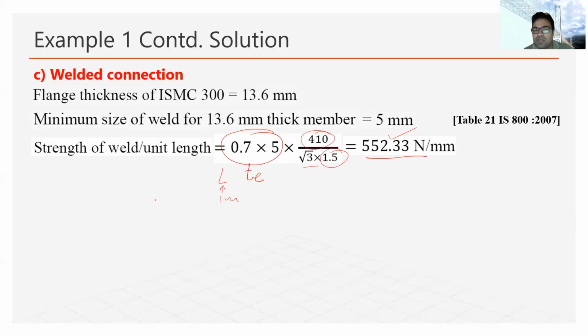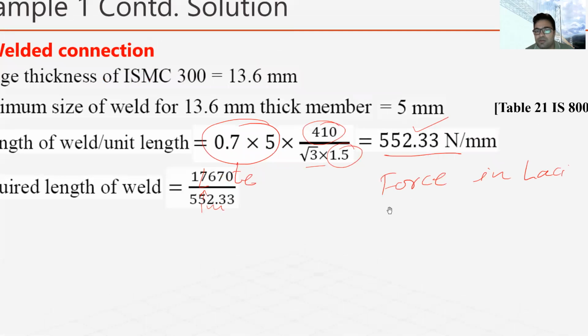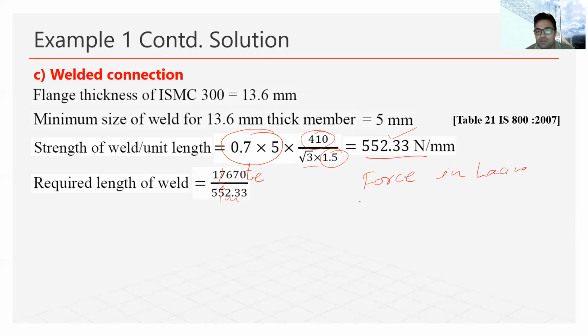Now we are going to find out the length of weld because we already have the force. The length of weld will be calculated as the force in the lacing bar upon the strength of weld per mm length.